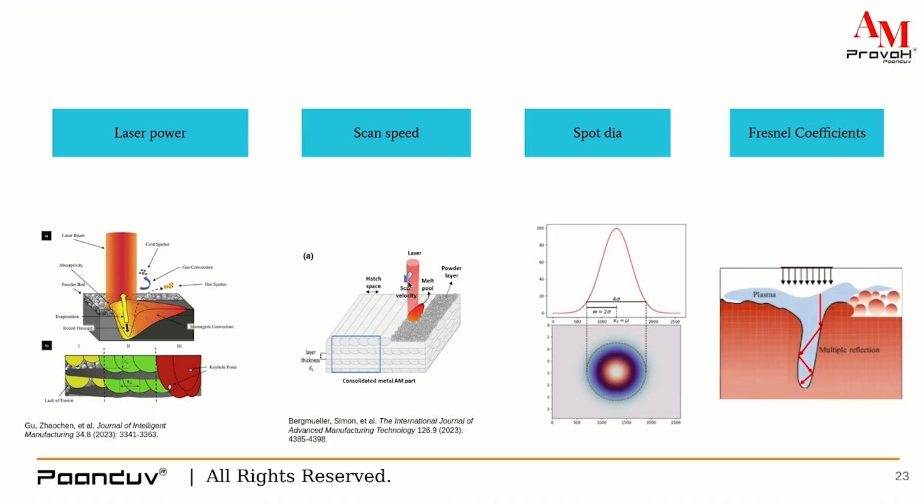Exactly where the laser is, the temperature will be very high, but if you go across different lengths, the temperature difference becomes very high, so that temperature gradients are even higher. And hence the resolution to that is, you can preheat your substrate, and that will change the temperature gradients occurring into your system, and which will eventually mitigate the defects.